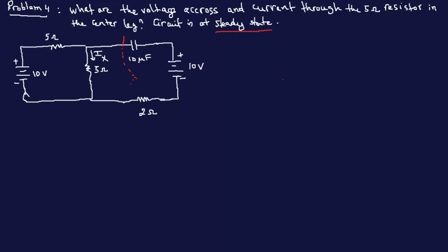There's nothing going through there, and so we can just apply KVL again. If you don't remember that there's no current flowing through the capacitor in a steady state DC circuit, then you're going to struggle here, because you're going to be like, okay, KCL, current here, here going in, and then you're going to struggle with the capacitor here. So that's a rule that's very important.